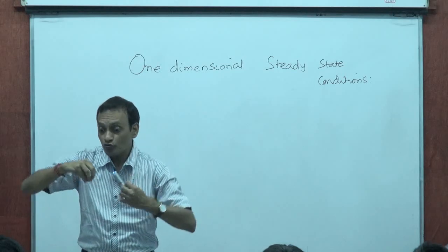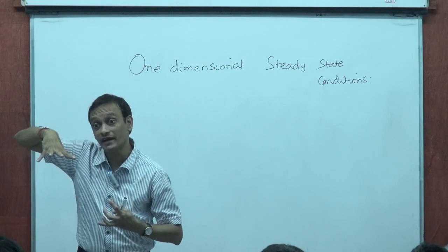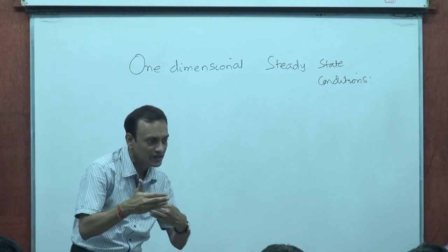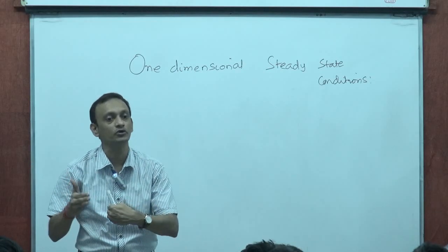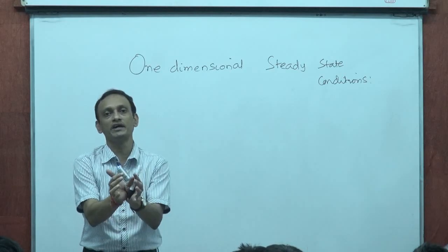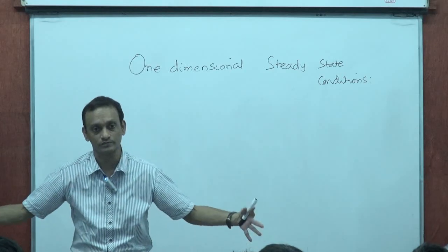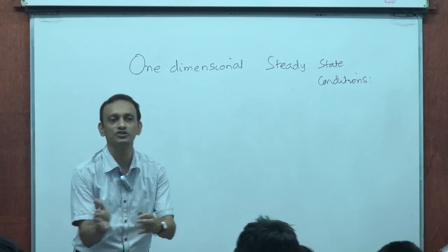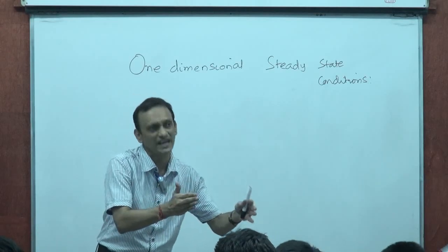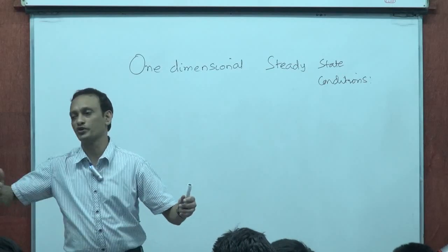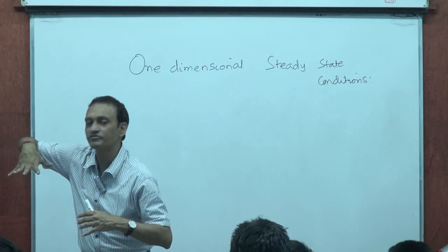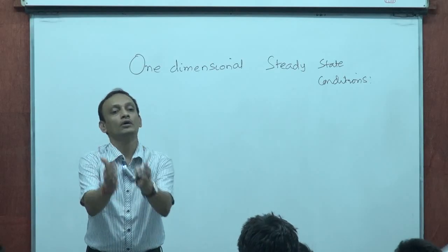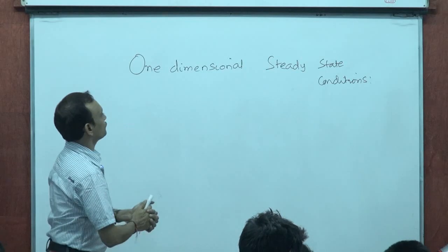In the sense, flow of heat could be radial. So that's in different directions, but that also in effect is one dimensional because it's all characterized by the radial distance from the origin. So one variable characterizing the flow of heat and therefore one dimension. It doesn't necessarily mean heat flowing along a straight line. It could be flowing in different directions.